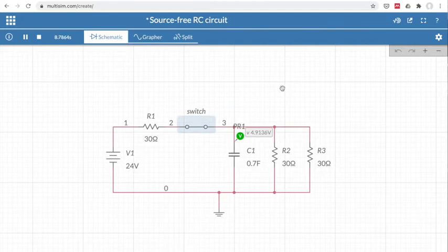While the voltage is still changing, or in this case still climbing up, we call it our transient response, or the temporary response, because the value of the voltage is still changing with respect to time. And you can see that because we have a voltmeter connected here, and it gives us a virtually real-time measurement of the voltage.